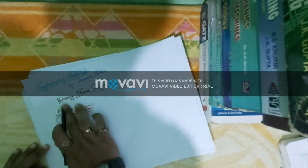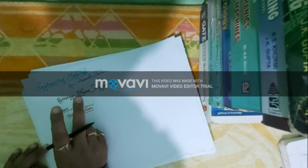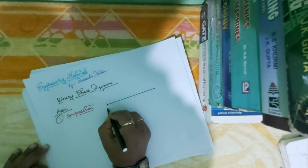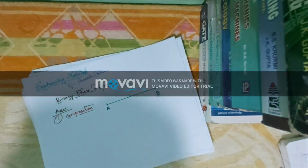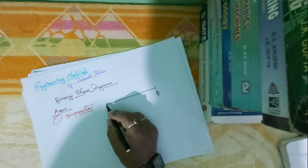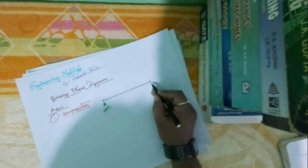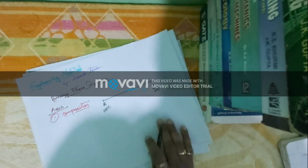So as we are talking about binary phase diagram, which consists of two components, here in composition there will be two components. On the left hand side, that is A component, and right hand side it is B component. Whenever we go from left side to right side, at the left side A is 100% and B is 0%, and at the extreme right side B is 100% and A is 0%.